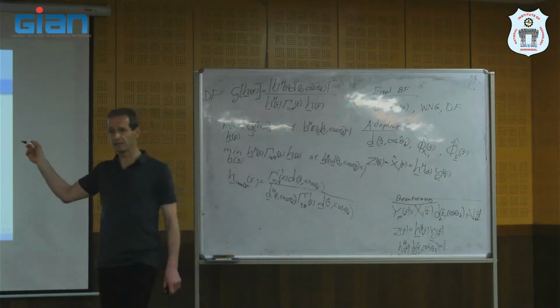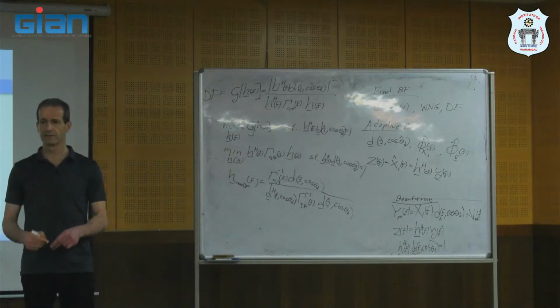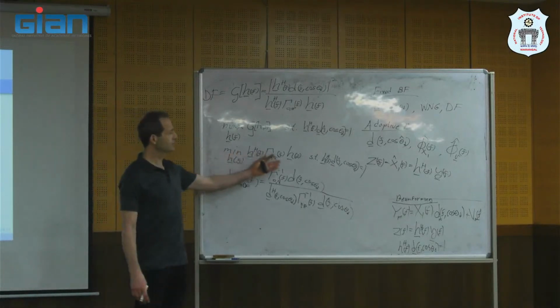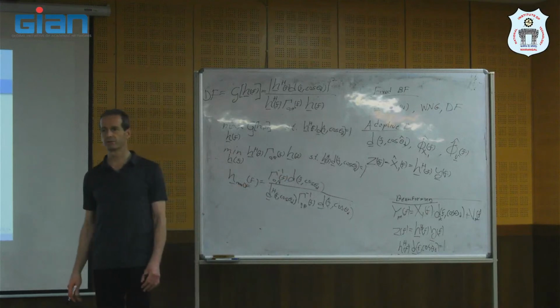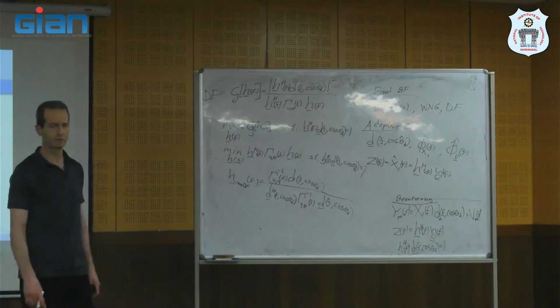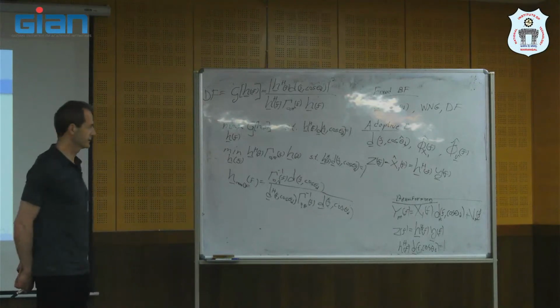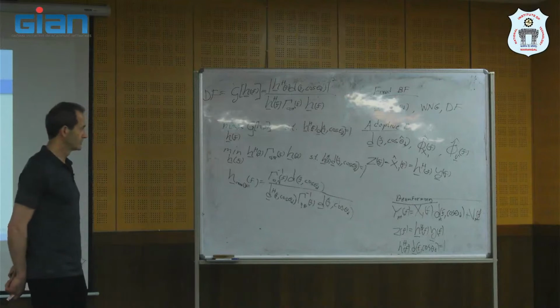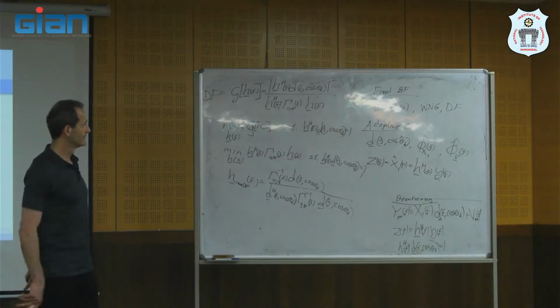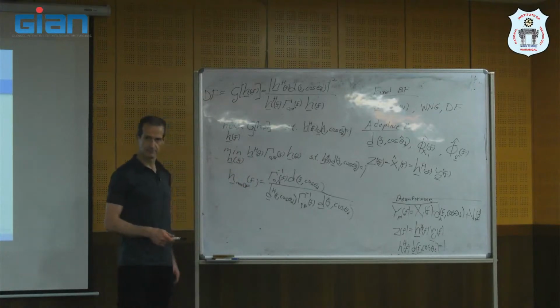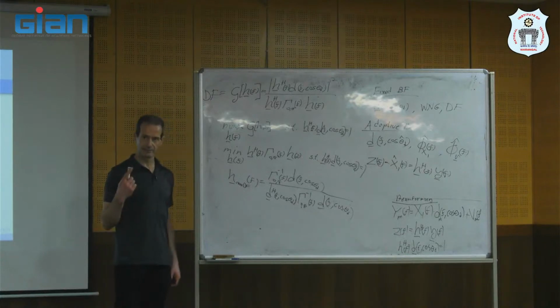So if you did the last assignment, it's actually very similar. For these kinds of problems, you know the straightforward solution, using a Lagrange multiplier. Once you prove it, you find many of the MVDR, directive, superdirective filters, and so on. So it's important that you know how to solve an optimization problem like that. So this is the filter that maximizes the directivity, the maximum directivity that can be achieved.